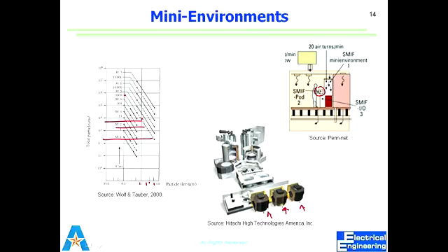There is a pass-through in the clean room. You guys have seen that? You must have been told about that during training. What is a pass-through? It's a small window in the wall. It's used if you want to move something in or out, you don't hold it and step out. It has two doors, one in the clean room, the other to the outside. Those two doors cannot be opened at the same time, right? So you place stuff in there from one side, you close it, and once you get inside, you open the other side and take it out. You don't leave your stuff in there, because that can contaminate other people's stuff, whatever they're moving. You'll see many things there. Sometimes they're open on both sides.